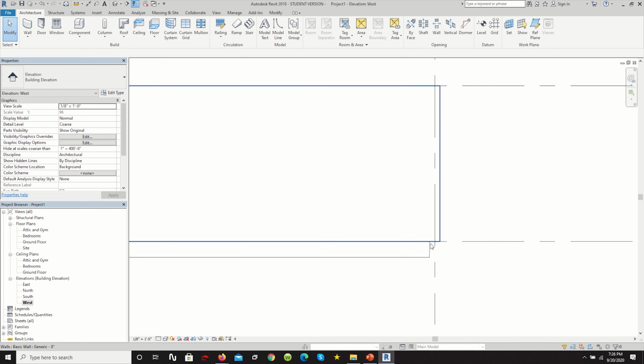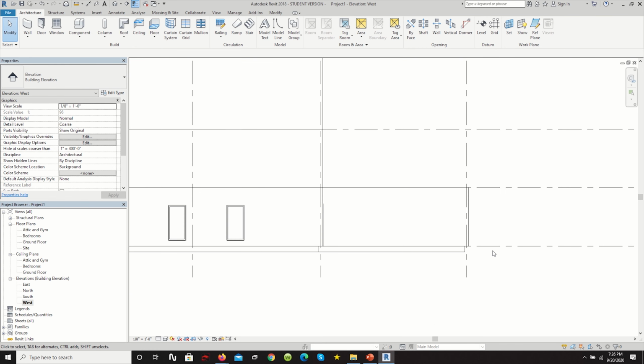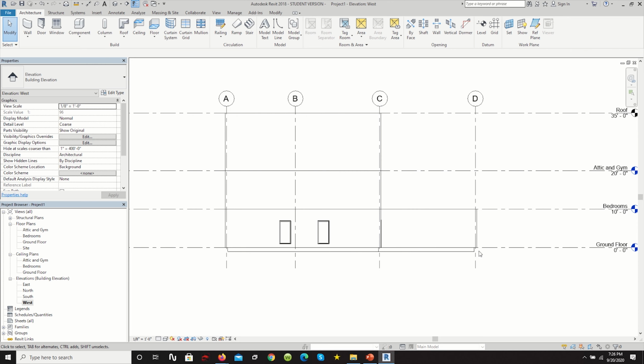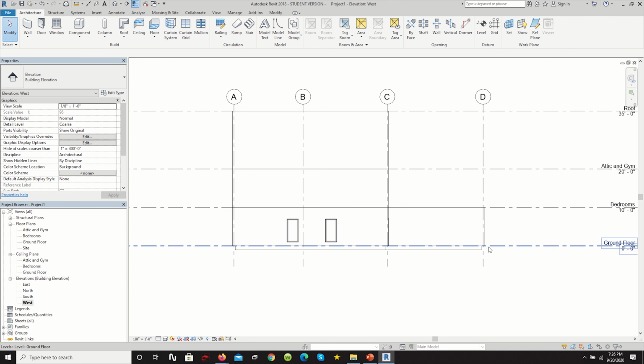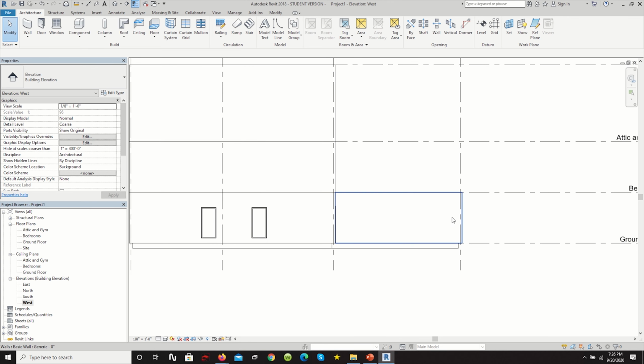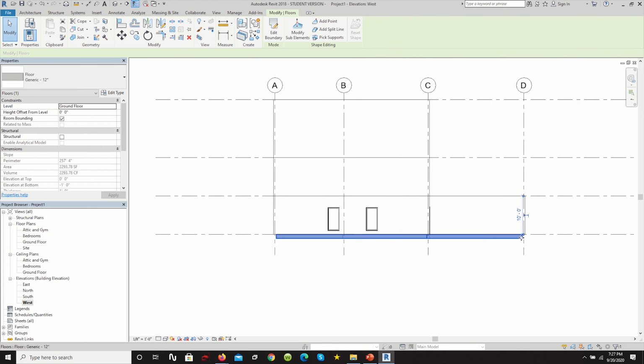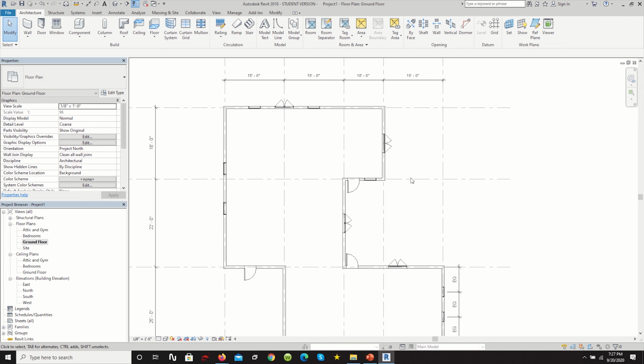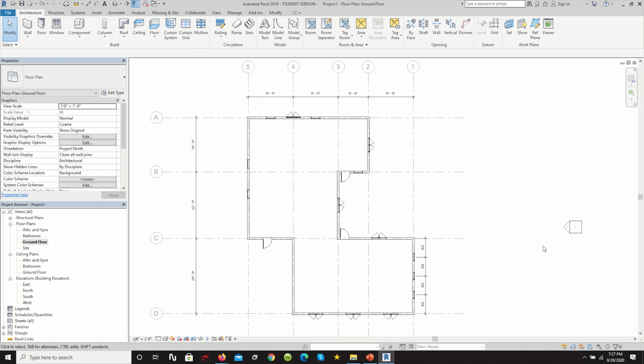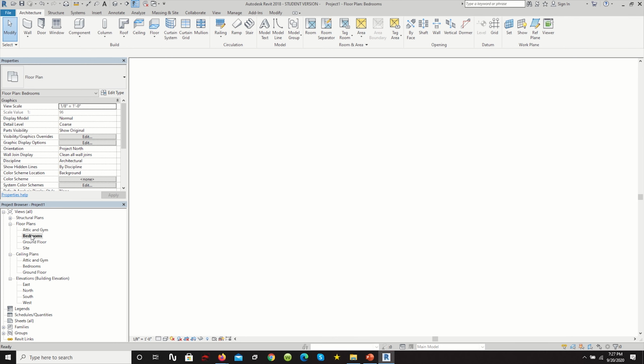So this is our floor, and our floor is expanding into the ground. And we're going to begin to mitigate this a little bit later in a future tutorial, but for now, we're going to continue to move forward. So let's go back to our first floor plan, and we pretty much have a decent layout. And now what we're going to do, we're going to repeat each of these steps that we did, adding the doors, the windows to the second floor plan and the attic floor plan.